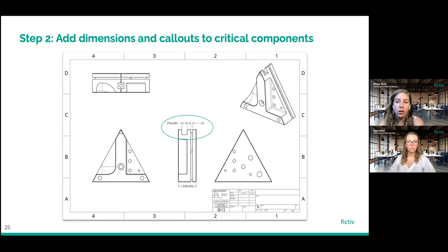On the other hand, this groove, the 0.13 width groove, is not quite as important, only 2 decimal points, and there's no tolerance associated with it. When there's no tolerance associated, as with this one, that's when we refer back to the title block where we have information about what tolerance to use when there's no tolerance identified. Here we have just the width of the part, and again, we can see this is going to be more of a precisely defined dimension.